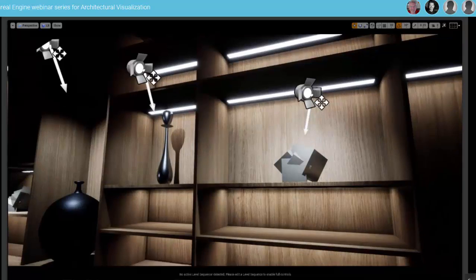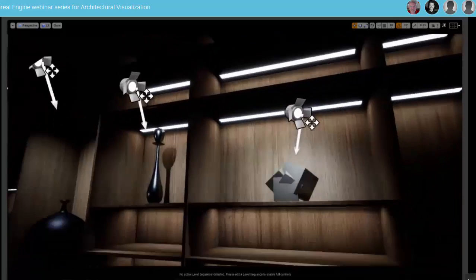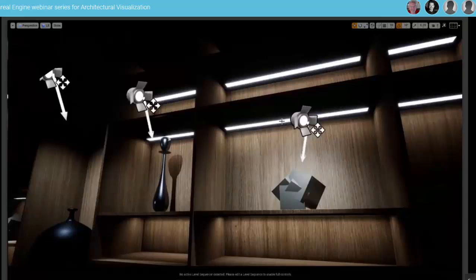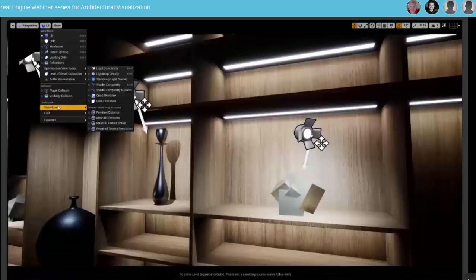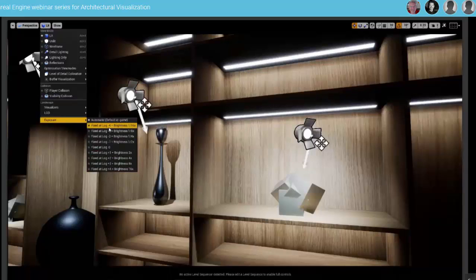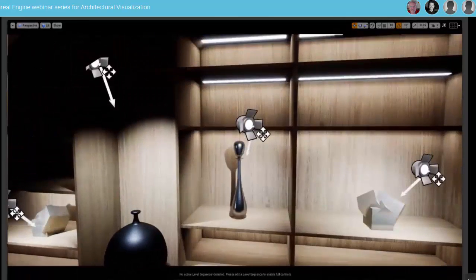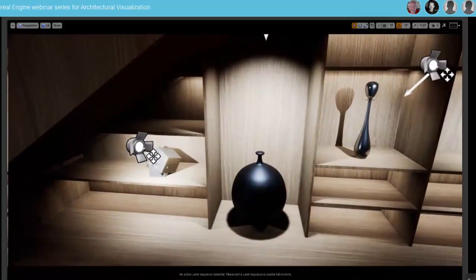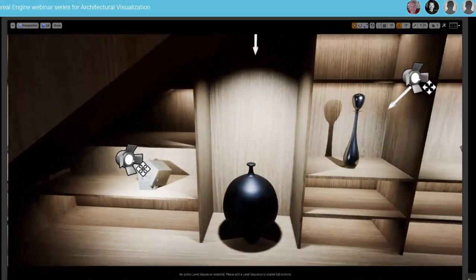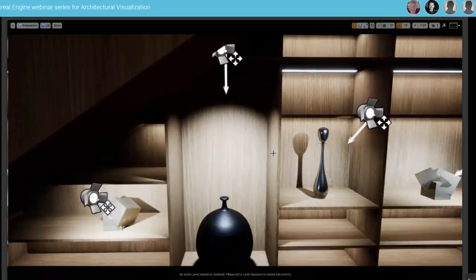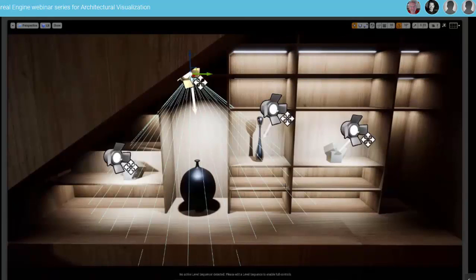So you can see how the tone mapper is working very, very hard here to accommodate the brightness of these lights. So that's why, when I work on the lighting, I make sure I fix it, whichever value you want. But it's good to try and not have that too complicated changing setup when you're trying to set your lights. So again, this sort of soft shadow here, and I've played around with the IES.